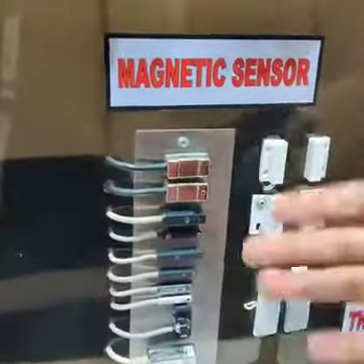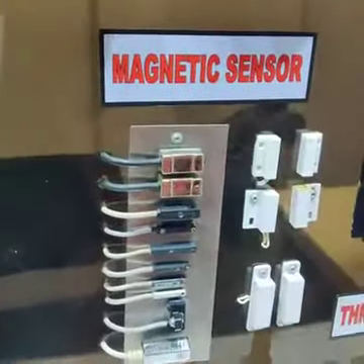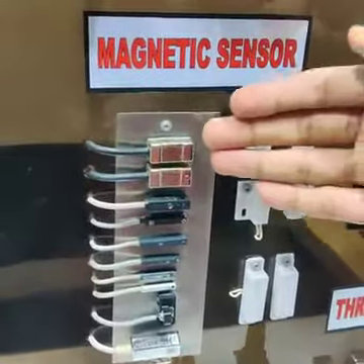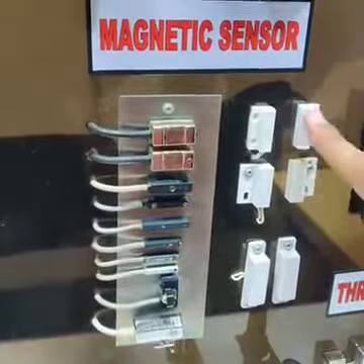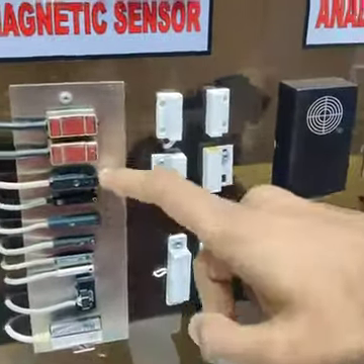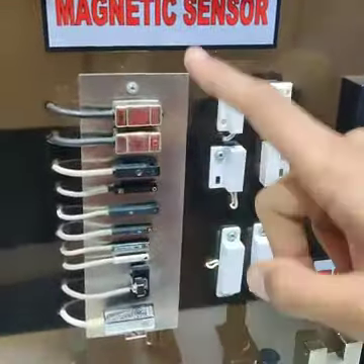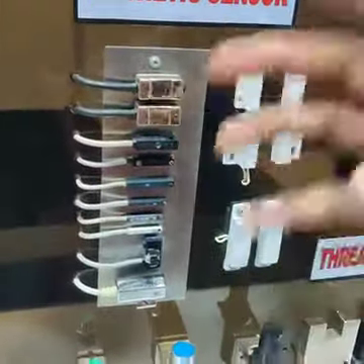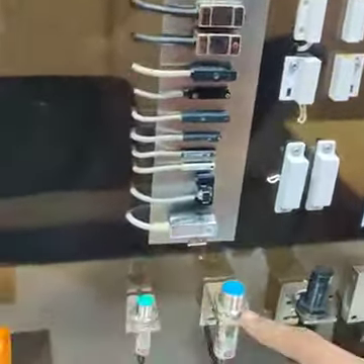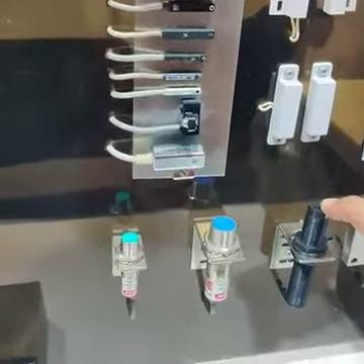These magnetic sensors give the output when the target is made up of magnet and comes in the sensing range. We have different shapes. You can see that we have different shapes. They are used in door locking mechanism, and mostly these sensors are used in pneumatic cylinder to check the position of the pneumatic cylinder for the feedback system. And we can see in cylindrical type we also have the pneumatic sensor.